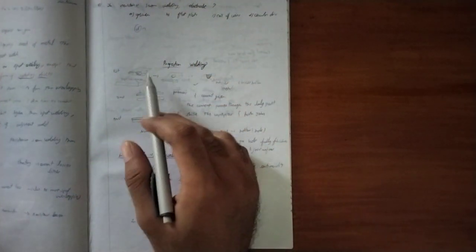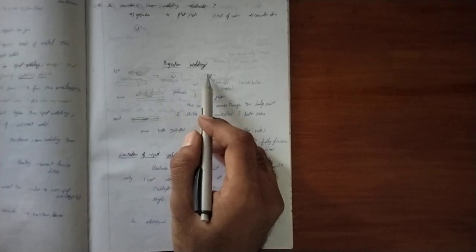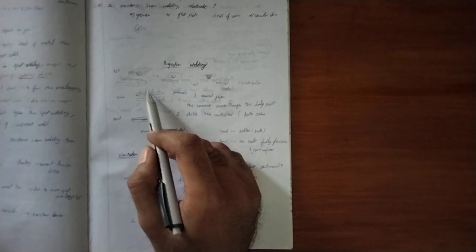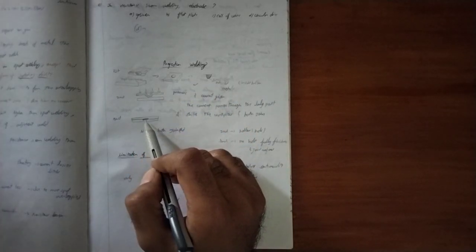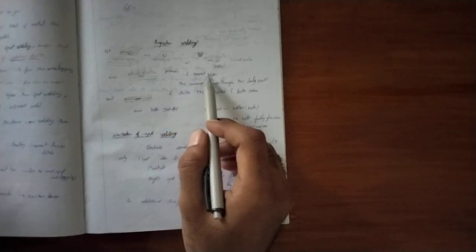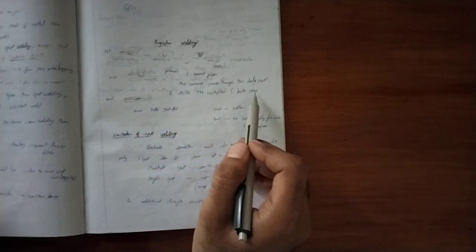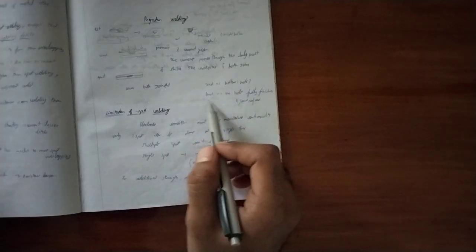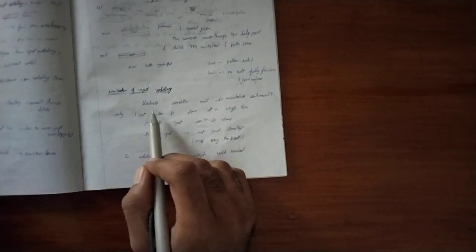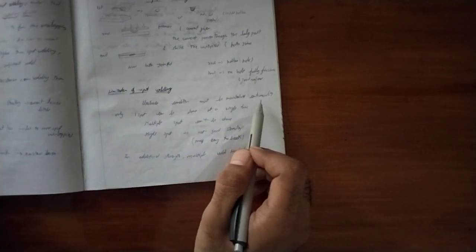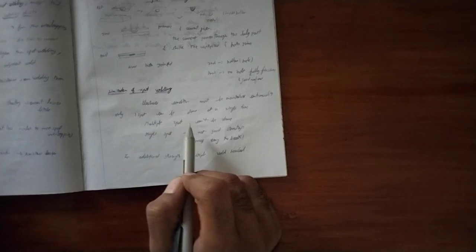Next one, projection welding. A little bit of projected area is formed, and we apply pressure and make this kind of projection towards the joint. Now pressure and current are given, and the current passes through the bulge part and strikes the workpiece, and both are joined. A limitation is that electrode condition must be maintained continuously in one spot, so multiple spots can't be done.